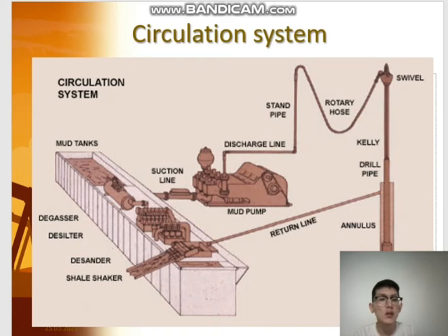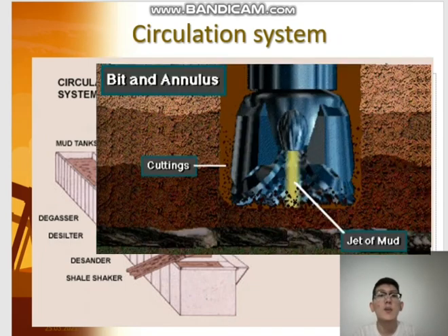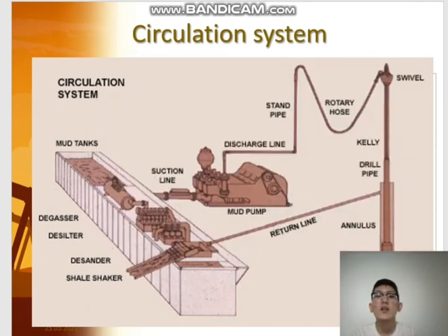Here we have our drilling bit. At the bit, the mud jets out of the openings or nozzles in the bit, and the jets of mud move cuttings away from the bit, and the mud then continues up the annulus, carrying the cuttings with it.